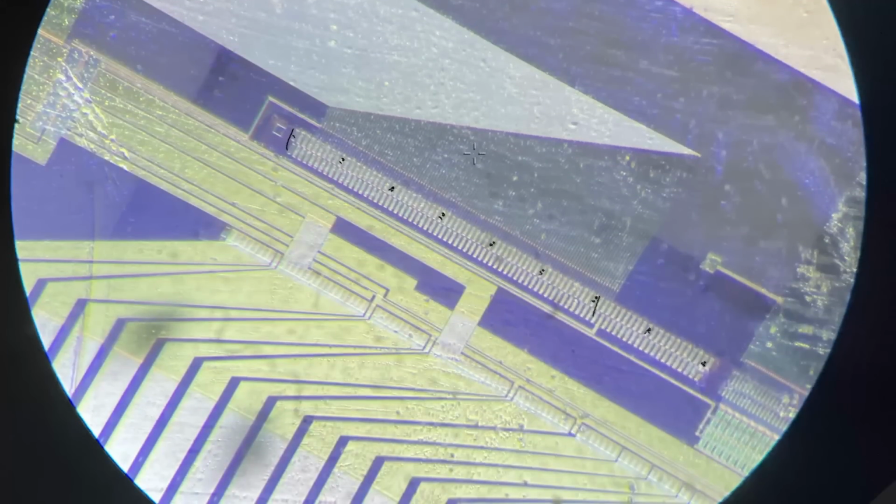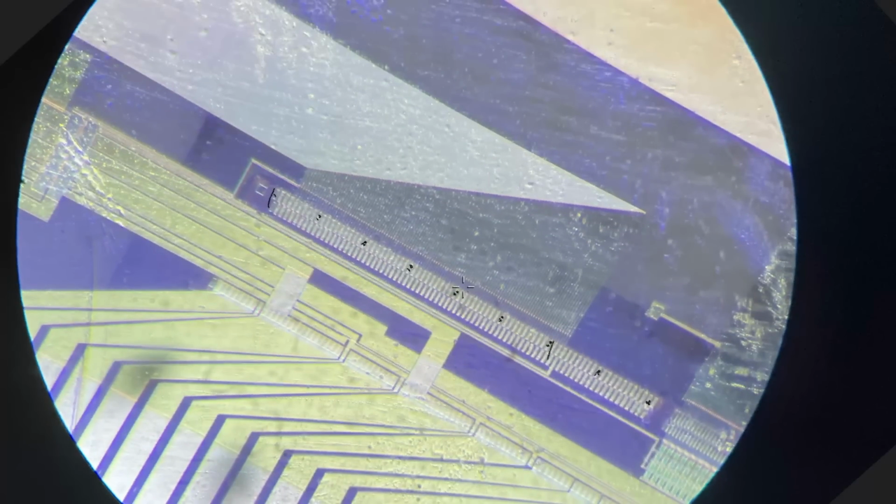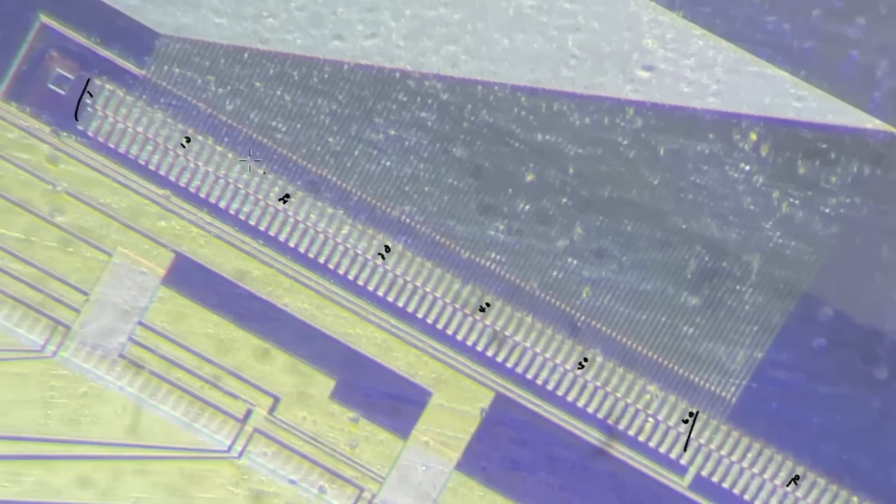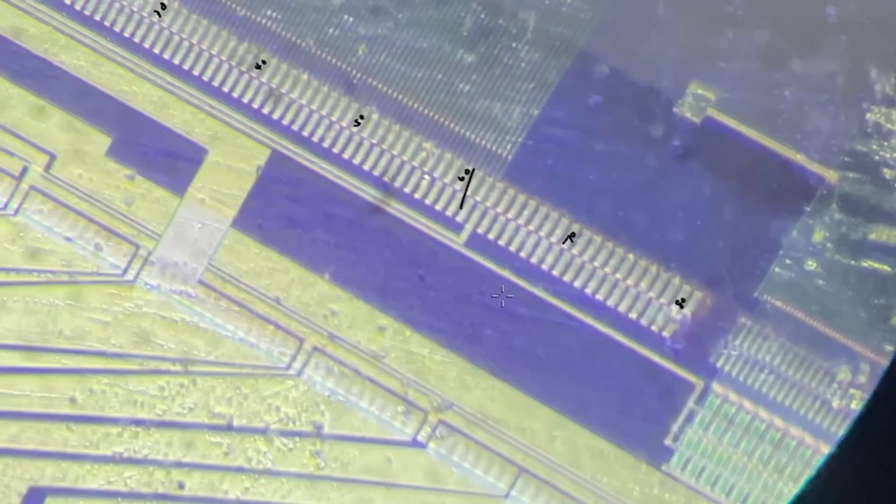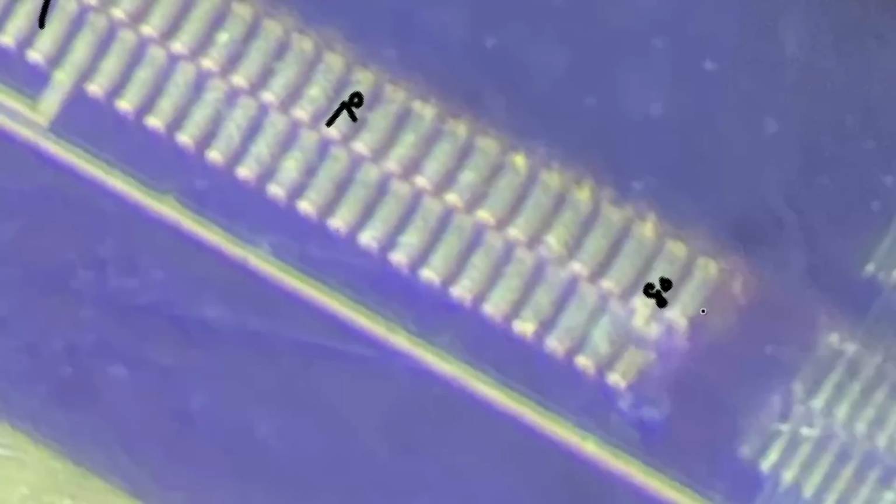This is zooming in onto the edge. So these are the Y driver lines. If I zoom in, I can start to see these individual lines, and so I can start counting. In fact, I've finished counting here, and I count a total of 80 pads on one side, so about 160 pads entirely. The other edge also has pretty much similar sized numbered pads, so we're counting about 320 of these pads, so we know the vertical resolution of the chip is probably around 320.